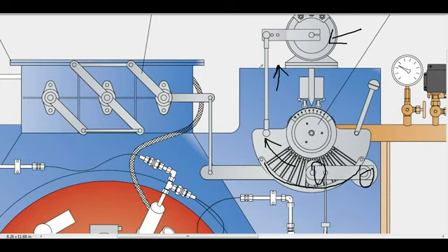As the link goes down, alright, I'll just clear it off. Now if the combustion automation system gives the servo motor a signal to reduce the fuel, the link comes down, and as the link comes down, the cam profile moves in this direction assisted by the rollers, and this moves 5, 4, 3 and finally 1 and then 0 over here. So this is the cam and cam profile.